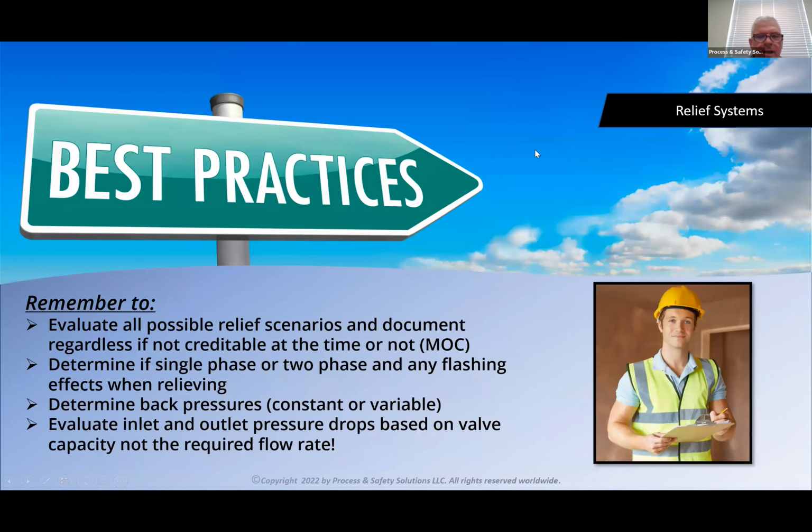So I tried to cover most of the scenarios that we see in terms of sizing and back pressures and errors that are typically made. One of the things to keep in mind is to always evaluate all possible relief scenarios and document them, regardless of whether they are credible at the time or not. Remember, it may not be credible, like we talked about the blocked-in case, or the pump feeding it may not overcome that at this present time, but by documenting it, we have that information in the future should we make any changes to the system.